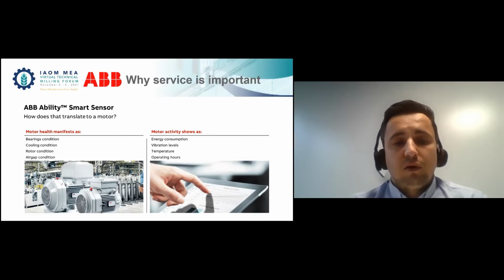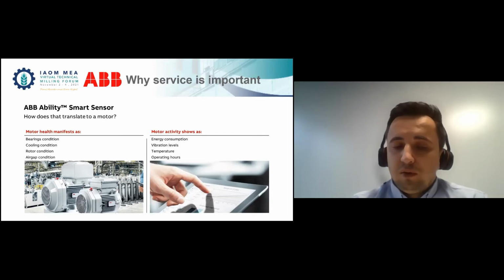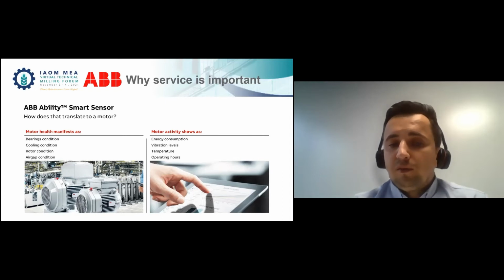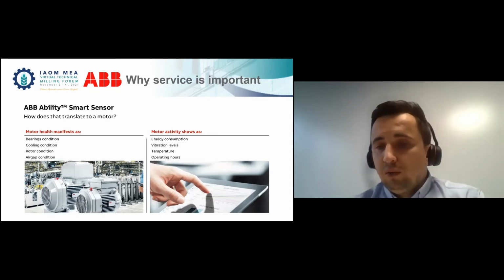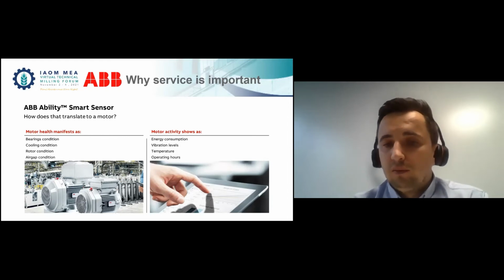The sensor is ensuring that the bearing condition is good, the cooling, the greasing. If the bearing vibration starts to exceed the allowed values, then the smart sensor pushes you a notification over smartphone, email, or however you want.